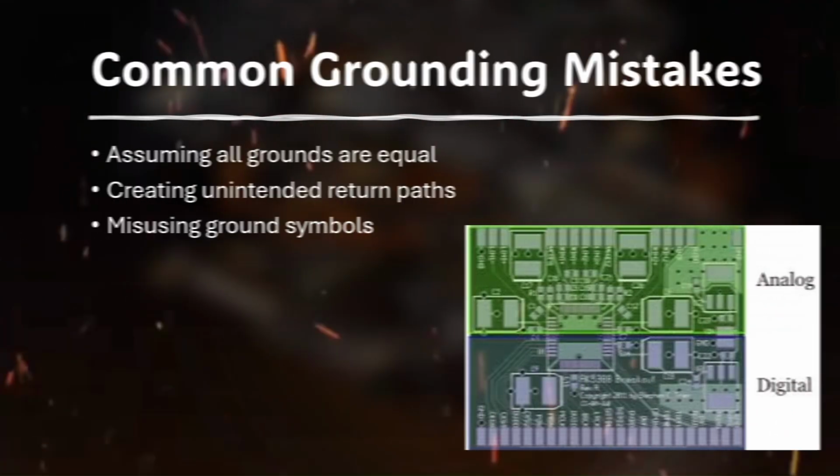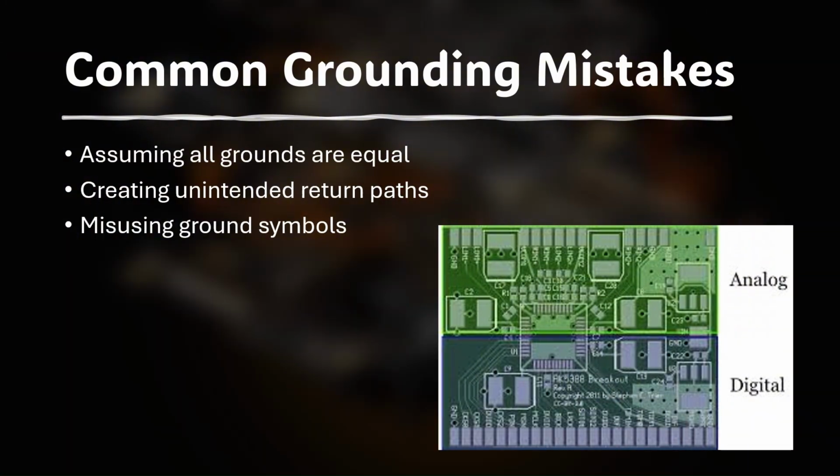Common grounding mistakes. One of the most common beginner mistakes is assuming that any ground symbol means the same thing everywhere. In reality, the symbol can represent very different physical connections. Understanding what type of ground you're dealing with is critical for both safety and performance.